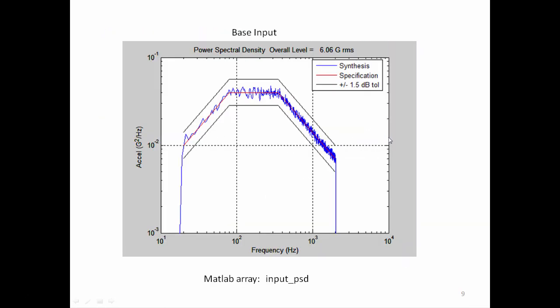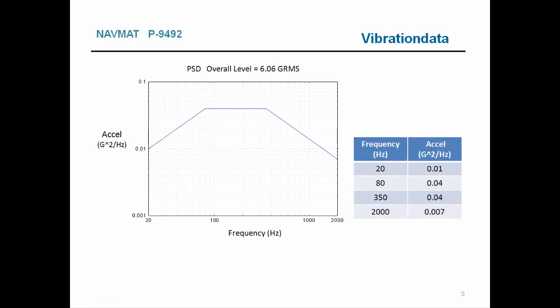Now if you go back to our, let me go back clear to the spec here. 200 hertz natural frequency. Now that's in the flat portion of the PSD. And we had sort of a rule of thumb for Miles' equation that we could use it if the PSD was flat over at least one octave on either the lower or higher frequency end of our natural frequency.